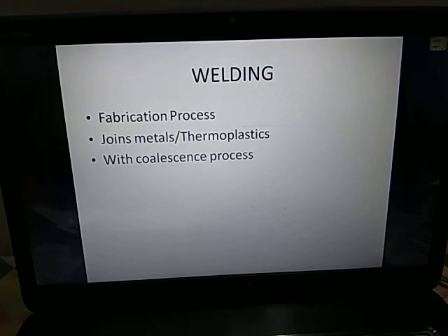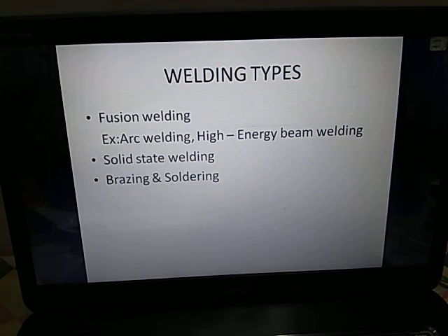Here the main purpose of welding is joining metals or thermoplastics. There are different types of welding operations, like fusion welding, solid state welding, brazing and soldering. Let us discuss fusion welding. In fusion welding, the operation is performed by means of high heat.